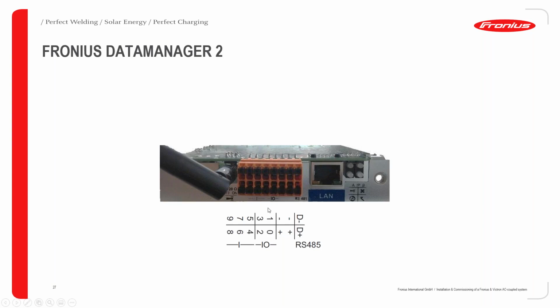This is where you can also connect, let's call it, external relays from ports 0 to 3. And this is where you can also send input signals. So maybe you want to control the inverter power from port 4 to 9. Then over here, we've got your LAN connection, which can be used for Modbus TCP communication, or it can also be used for your wired connection through a router to the internet. Then on the right-hand side, we have your LEDs, and these are your status LEDs for any connections on the communication.